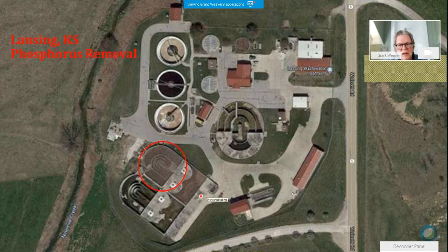And the trick to doing that is turning down the mixing to the point of turning it off, allowing some sedimentation to occur. As it does, that settled bacteria creates an anaerobic blanket at the bottom. And then periodically, at least once a day, resuspending that material so that it doesn't sit there too long and decay. And secondly, so that you don't lose your mixed liquor, all start to settle out in here.